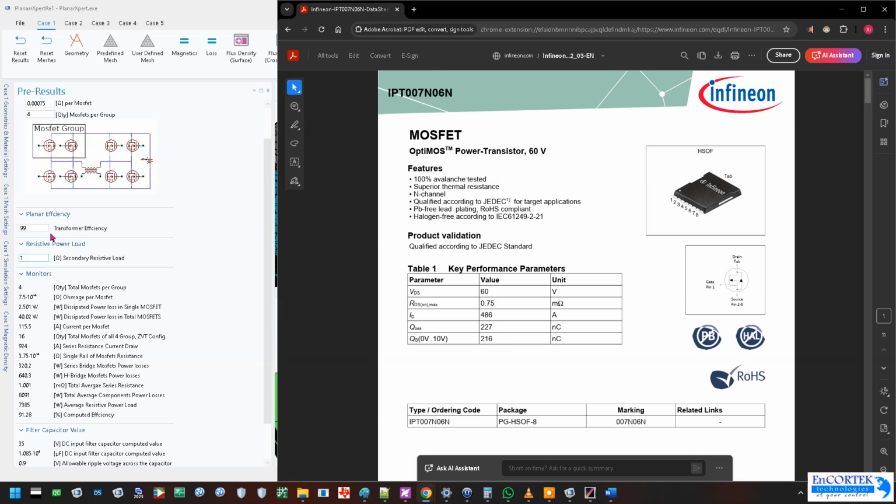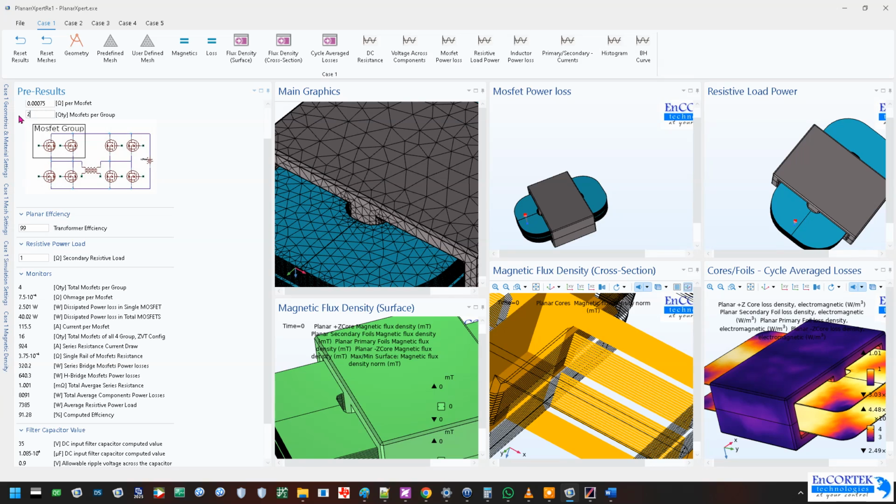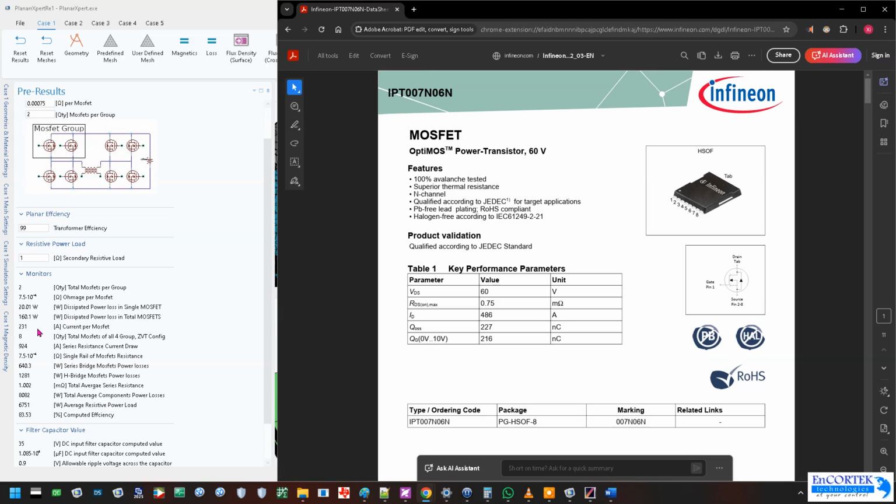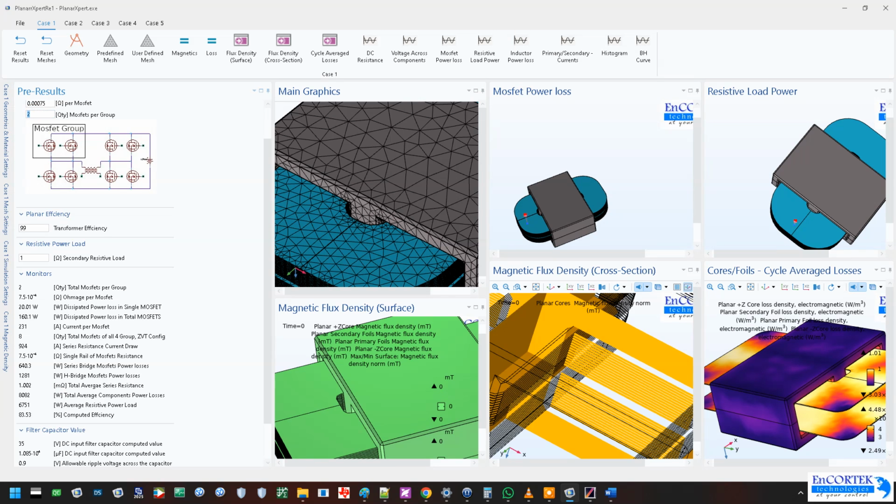So we could pretty much use 2 MOSFETs, right? And we're using half of the current, right? So if we're using half of the current, 2 MOSFETs will be fine, right? If I use one, it could work, but that is maxing out the current, and we have a voltage that will be developing across it, so the voltage may go up. So if we run one MOSFET, what we have here,